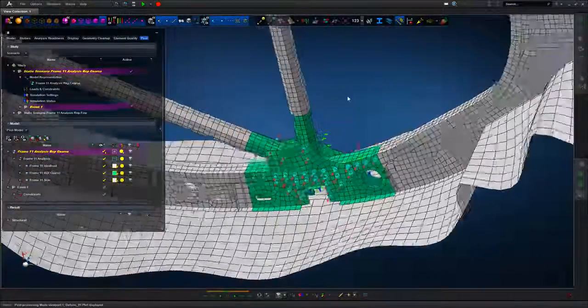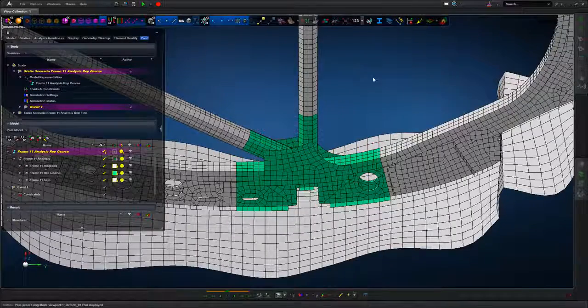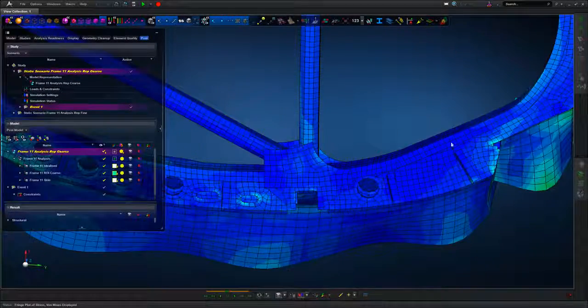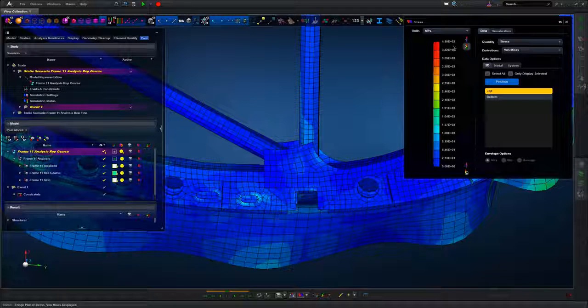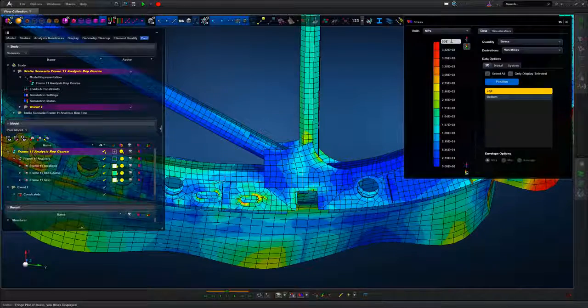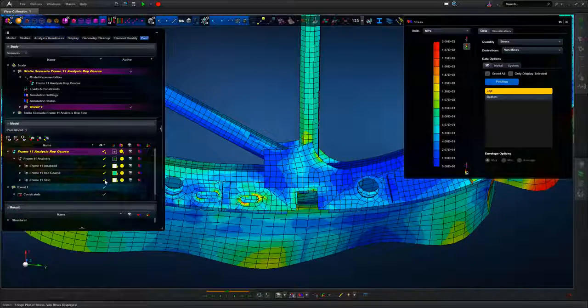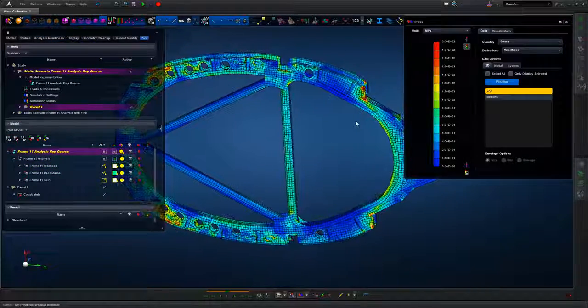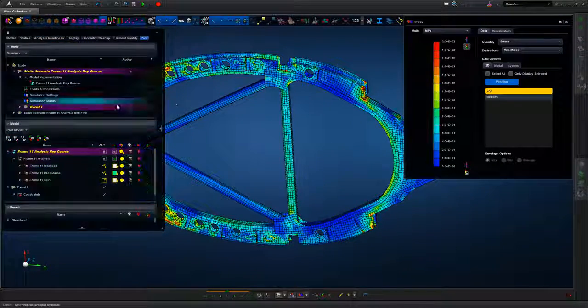So post-processing, first of all, for model representation 1, this is the coarse 10mm element edge length, which uses glued contact at the interfaces, and we can look at the stress levels developed, taking the skin out of view and setting the extreme stress limit to 200 MPa, and we can see the fringe that's developed at that level.